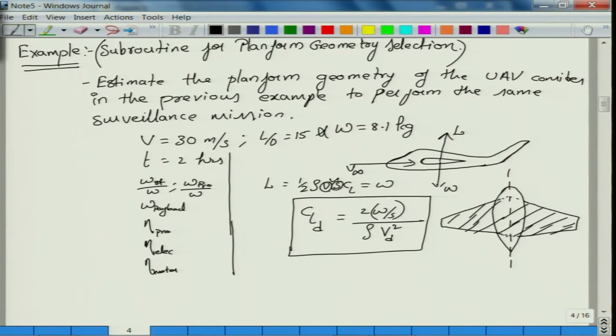This, when moving at this particular velocity, will generate the lift combined with some CL value, non-dimensional. The CL here talks about the cross sectional property, so you need to talk about the cross section of the wing, that means in terms of CL alpha, CL naught, alpha design and alpha at which CL is equal to 0, right. This we will handle for the time being. We assume that CL design is provided, given I have a certain W by S, right.